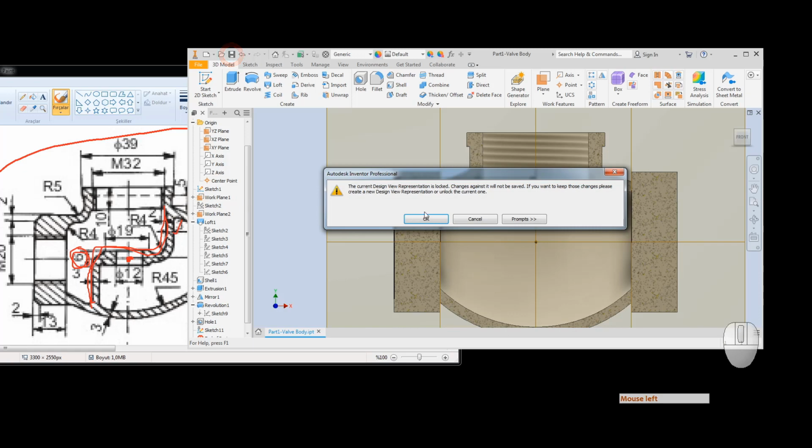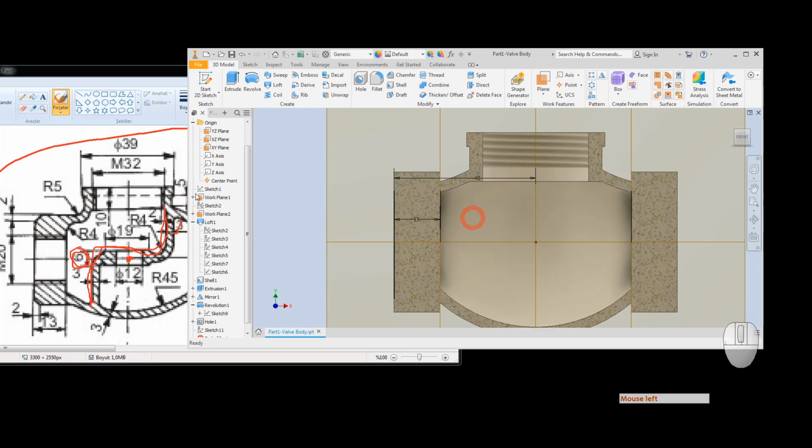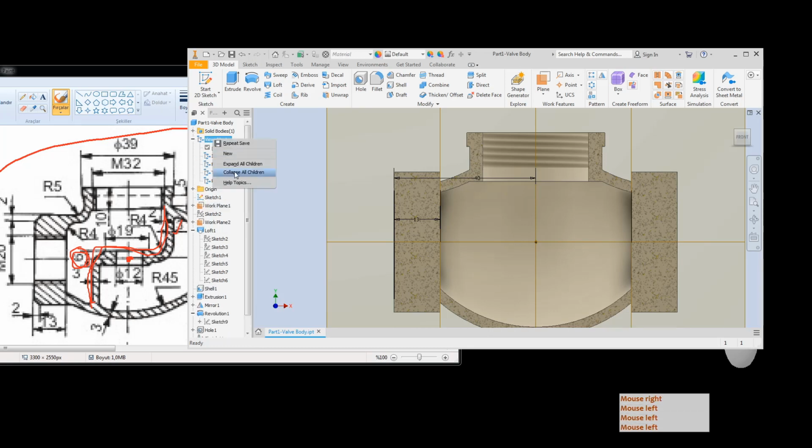let's start a new sketch, again XY plane, and this time I will just create this profile by creating a new sketch, which is this profile just comes from this inside and it will just go up to this point with the thickness of 66 millimeters here in the center part.